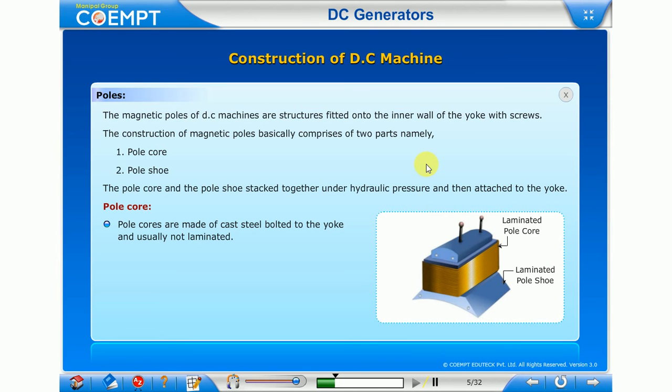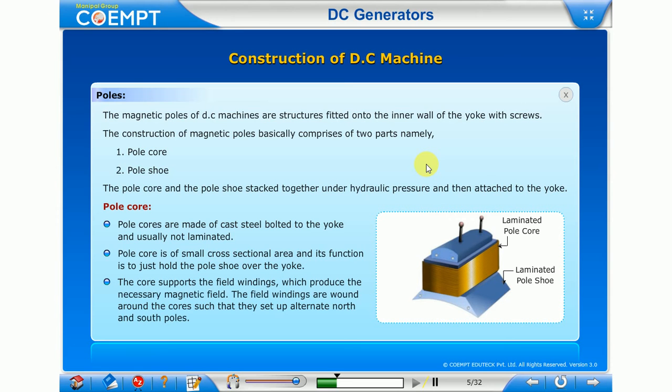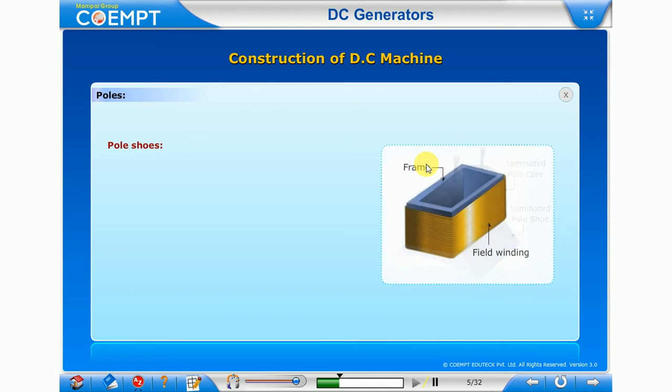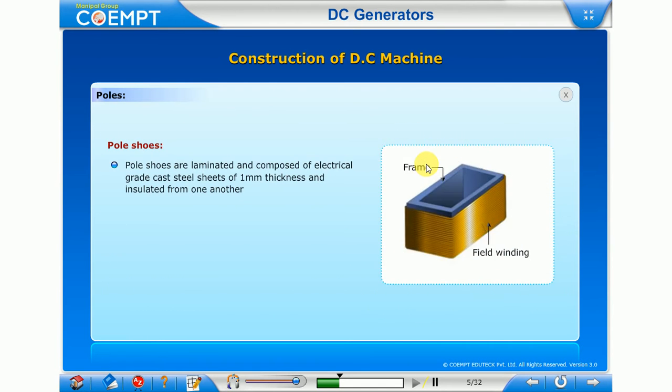Commutator. The function of the commutator is to convert the AC voltage induced in the armature conductors to DC voltage in the external circuit in general operation, whereas in DC motors, the commutator produces unidirectional torque. The ends of the armature coils are joined to the commutator consisting of a small number of wedge-shaped segments or bars of hard-drawn or drop-forged copper.